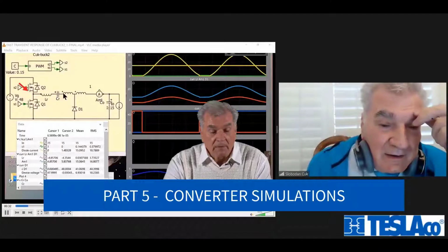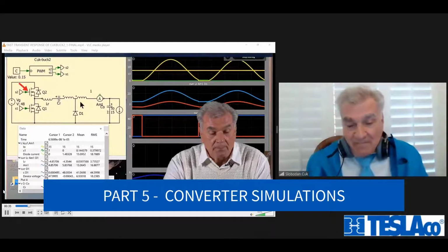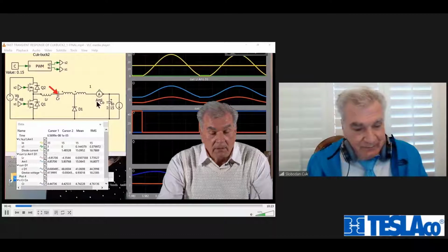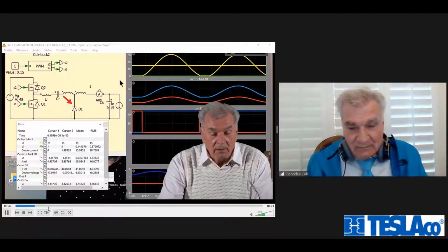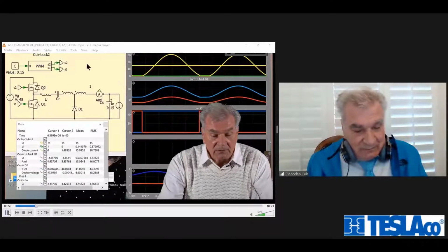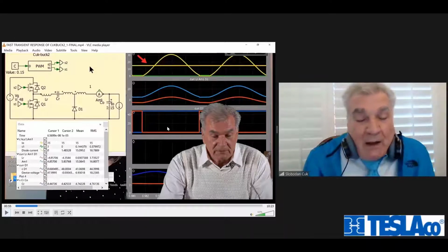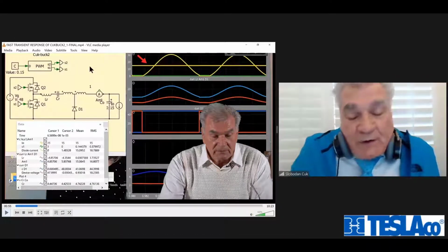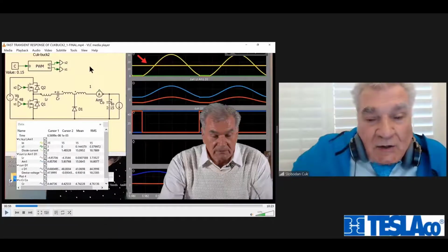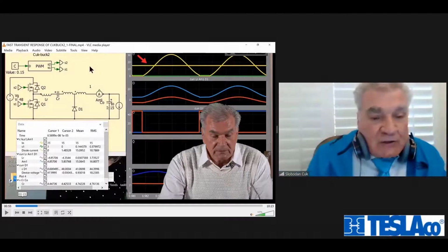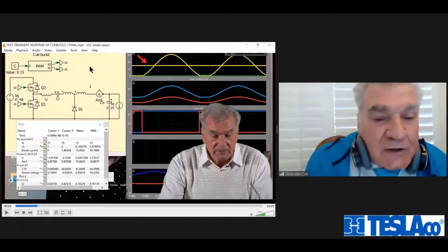On the input side, you have a resonant capacitor, and you have a hybrid transformer with its primary and a secondary, and you have a diode, and on the output, the secondary delivers current to the load. You see also waveforms here. Just to tell you what is new, as I said, now with switch mode power conversion, we are in charge of the circuit configuration, and we are in charge of everything extra which is put around that transformer to make it a transformer.